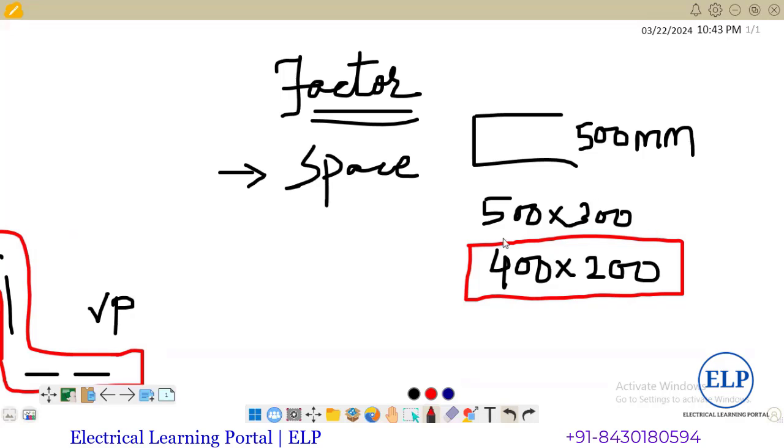In this case, you also have to check from the installation cost point of view, because there are a lot of duct pieces running in the project. All the duct pieces are in small lengths. Just imagine, there are a lot of duct pieces running, and these ducts will cost a very huge amount in the project. So you always have to check which size should be selected. This is a very important point. Suppose, for example, you are doing 1000 duct pieces, and in every duct piece you have a choice. You can either reduce 100 mm height, or you can reduce 100 mm width.